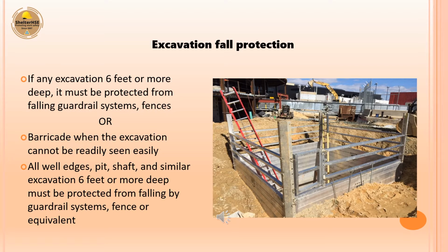All well edges, pits, shafts, and similar excavations 6 feet or deeper must be protected from falling by guardrail systems, fence, or equivalent.